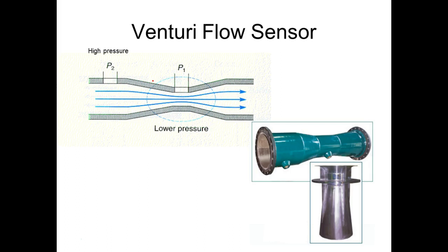Anybody that's got a pressure washer, normally they come with a big old tank on it, and then you can run a pipe and plug it into the side and put liquids in there. And when that high pressure or that fast flow goes past there, it goes through a Venturi, creates a vacuum and pulls that stuff right out of that container into your pressure washer. We do the same thing here. And we use this principle.